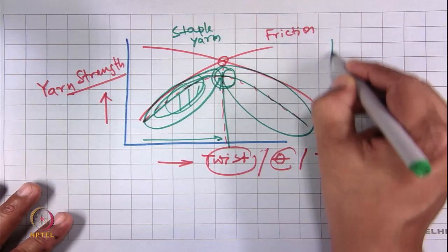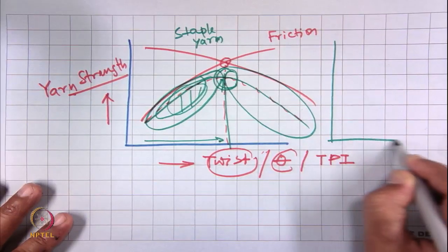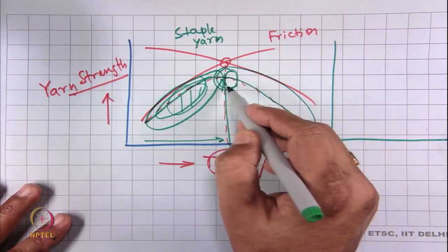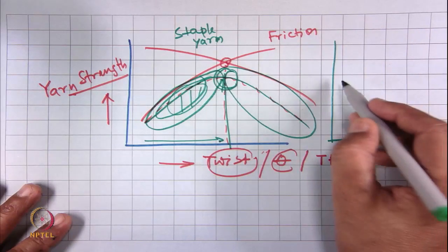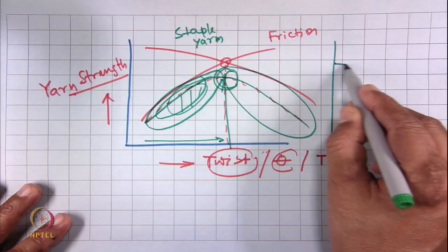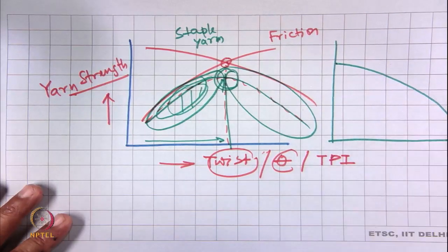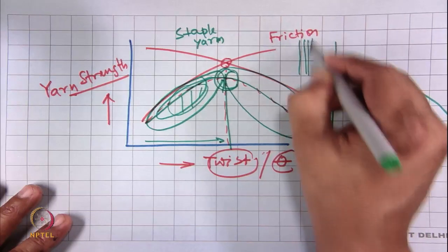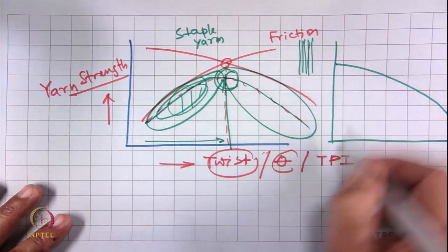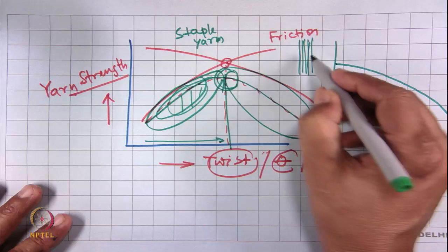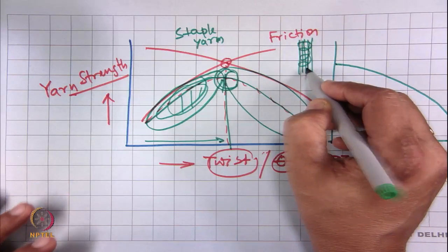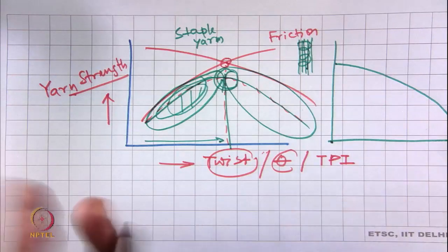Now, for continuous yarn, the obliquity effect reduces the strength continuously, but initially, when the filaments are parallel, that is the zero twist case, and a little bit of twist is applied, there will be a frictional assistance.